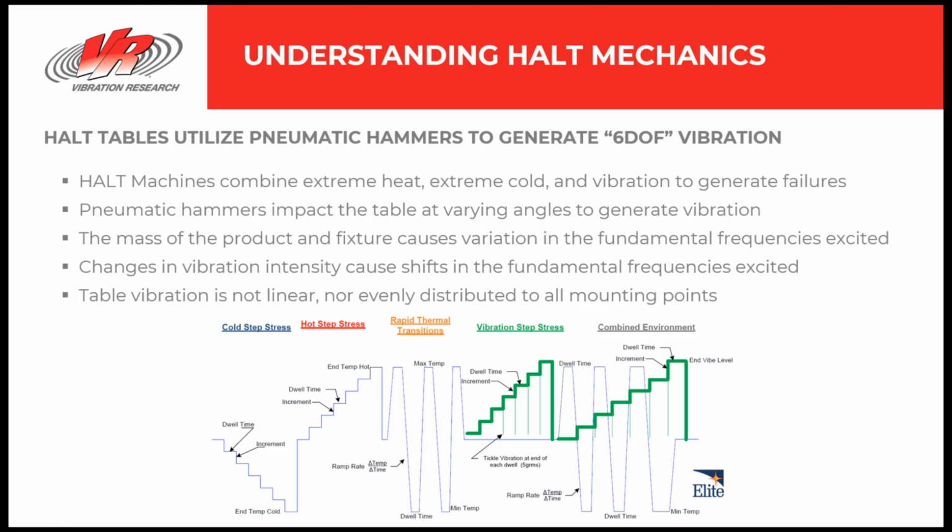One of the other notes that I learned in my research is that over 40% of HALT failures are generated by vibration fatigue. So vibration fatigue plays a significant part in generating failures on the table. Having a better understanding of what is happening to the product and how the product is being excited is critical to improving HALT analysis.